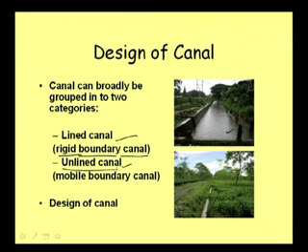Now, when we say that it can get eroded, it will depend on various parameters, like what the flow velocity is, how much the erosion can be, and what type of sediment the bed and the bank are made of. So, the type of sediment and the saturation condition, all these different aspects will come in, depending particularly on the formation through which the canal is passing.